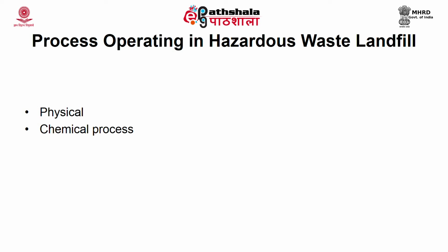The hazardous waste which is present inside the landfill will be subjected to a range of processes. It can be a biological process, a physical process, and a chemical process. The processes include redox reaction, complexation, ion exchange, adsorption, precipitation, neutralization, etc. The migration of leachate through the hazardous waste mass in the landfill will disperse and dilute the pollutants.